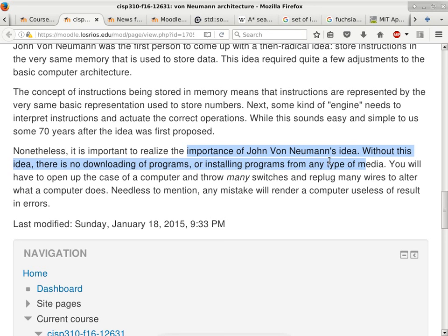So you have to do some certain exercises on the memory bus, just to find out, okay, I think RAM is located here, but how much RAM do I have? Is it 4K, 16K, or 32K kilobytes, right? Yeah, because people are not used to those units anymore. And so you have to do all these things with no assumption whatsoever that you already have RAM available. So you cannot use variables. You have to do everything without a variable for a while until you get to RAM.